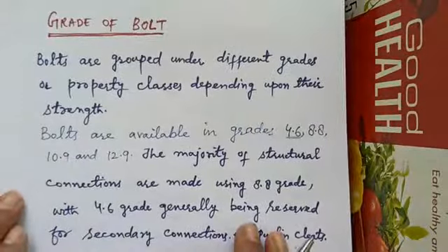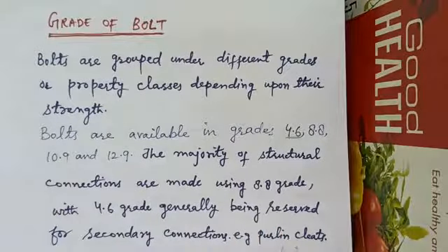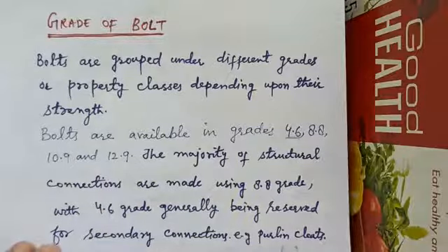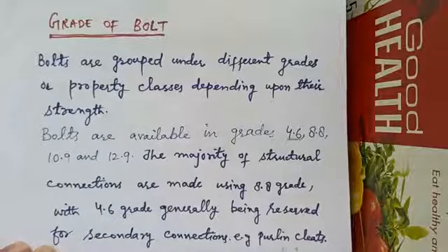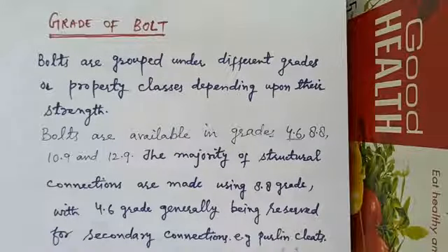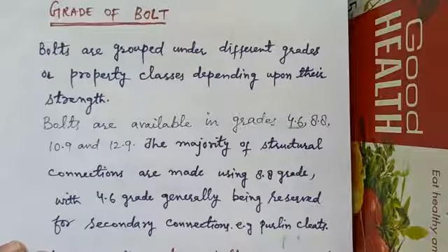Now let us discuss the grade of bolt. Bolts are grouped under different grades or property classes depending upon their strength. Bolts are available in grades 4.6, 8.8, 10.9 and 12.9. The majority of structural connections are made using 8.8 grade, with 4.6 grade generally being reserved for secondary connections, for